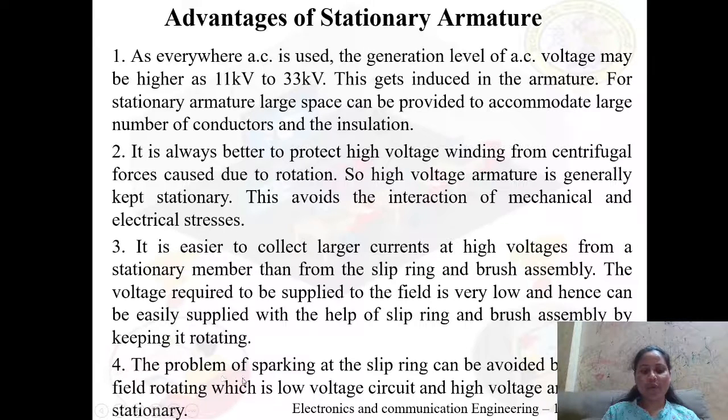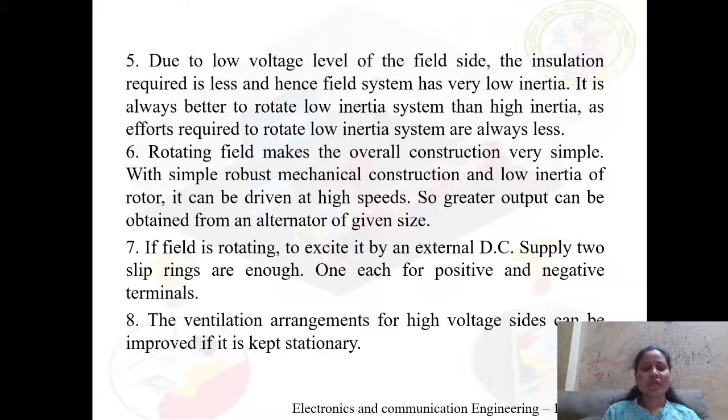The fourth advantage is the problem of sparking at the slip ring. We can avoid it by keeping the magnetic field rotating, which is the low voltage circuit, and the high voltage armature as the stationary part. Another advantage is that due to the low voltage levels on the field side, the insulation required is very little, and hence the field system has very low inertia.